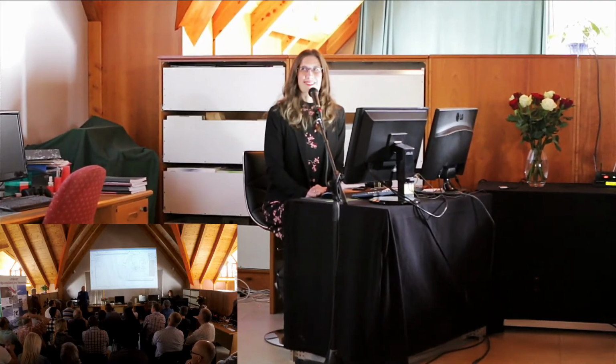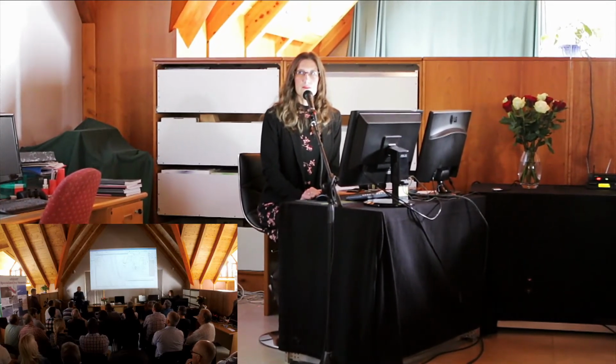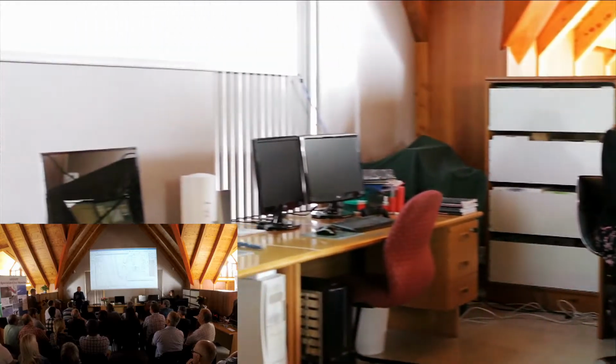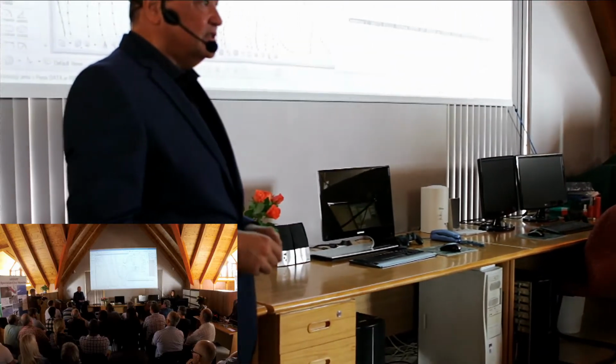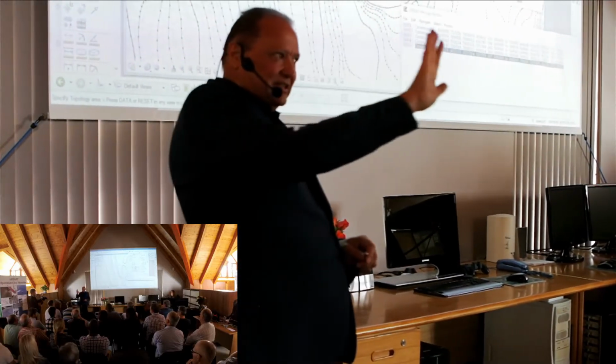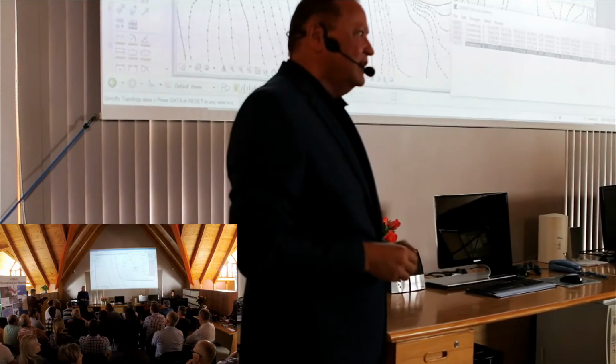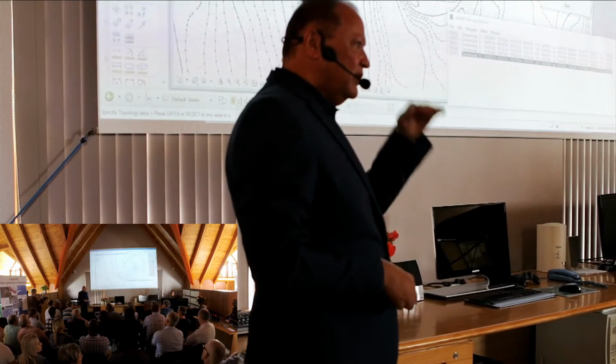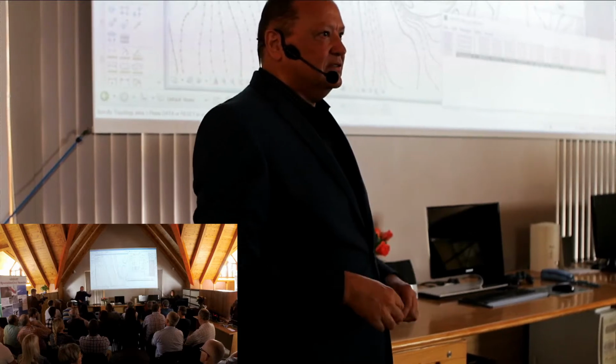So you can see the shading. That kind of goes in with that other question: now when I pick that contour, is the height going to stay the same? Yes. In a 3D environment, it's going to stay flat to the thing. But when you're working on the ground, then it's going to pick the height of that contour.